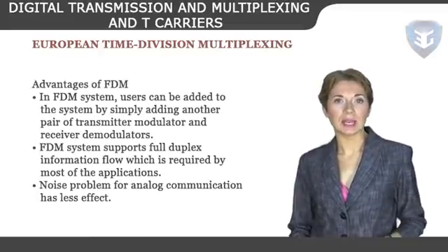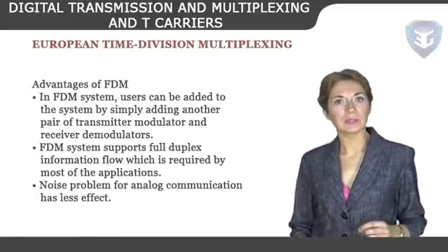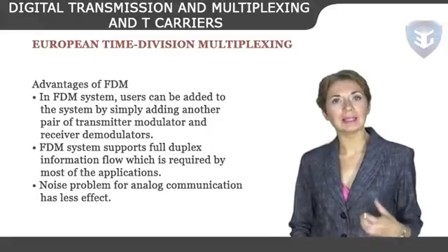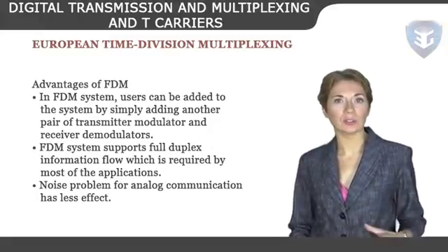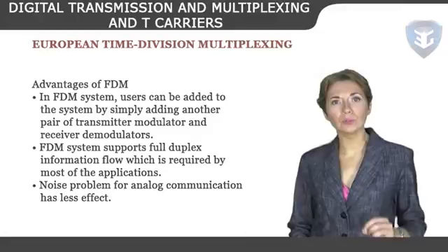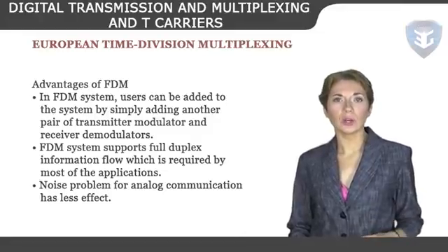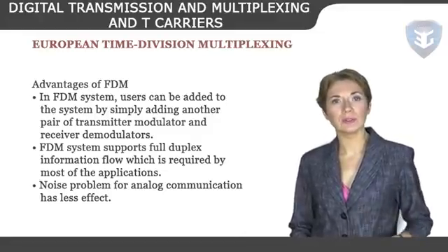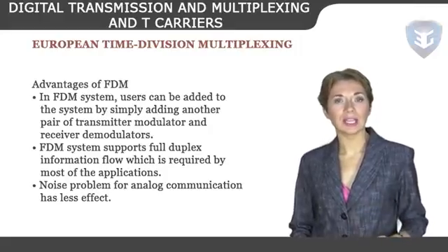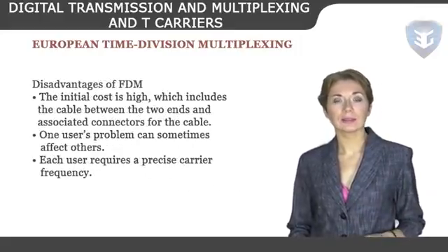Advantages of FDM. In an FDM system, users can be added to the system by simply adding another pair of transmitter modulators and receiver demodulators. FDM system supports full duplex information flow, which is required by most of the applications. Noise problem for analog communication has less effect.